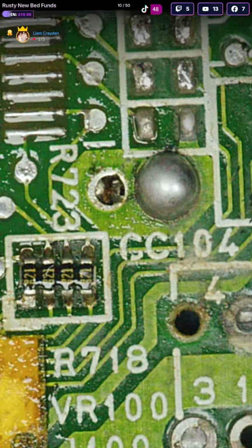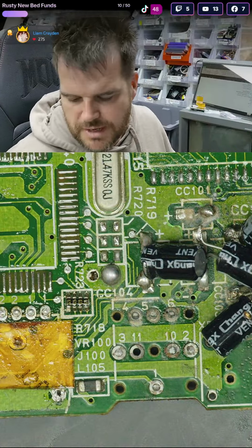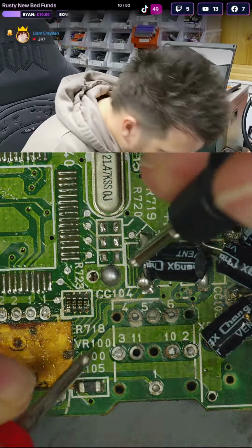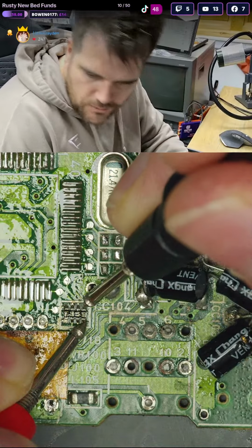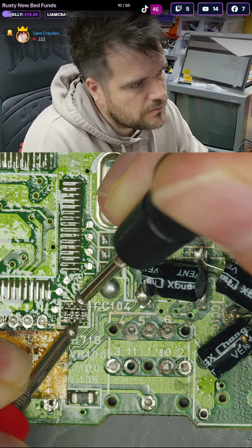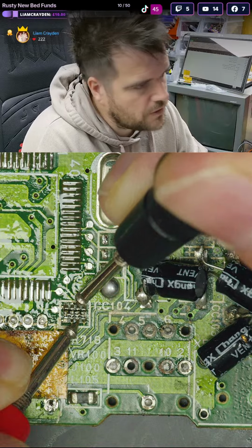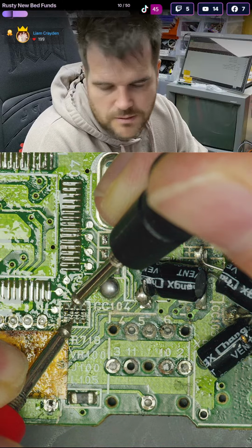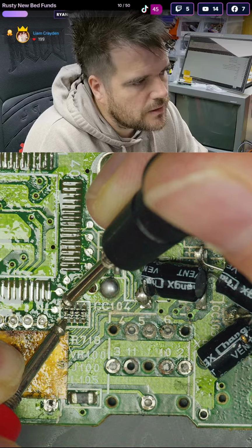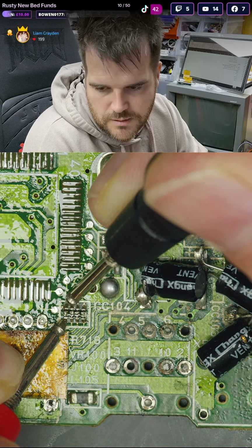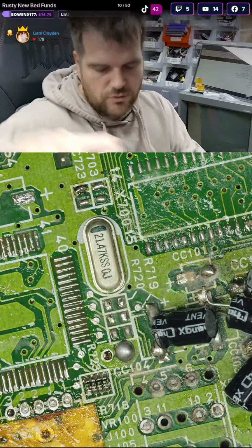And to test that, we will get the multimeter on and measure one, and they all say the same, so this is just going to be a string of 820 ohm resistors. And we'll measure them all actually, because if one's failed, this board isn't going to work. So yep, 820, 820, 820, yeah, so they're all good.